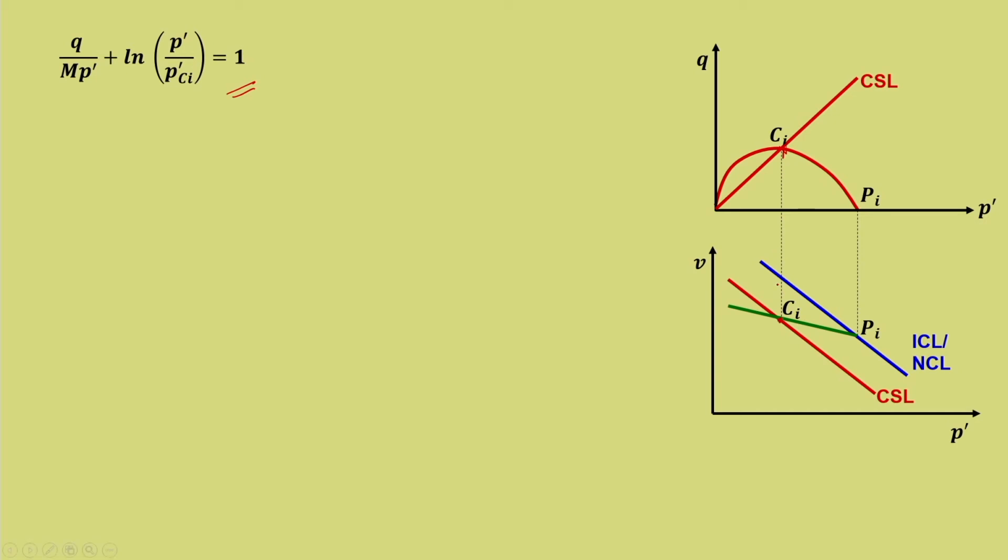So, what is the relationship? That is what we are trying to understand. When we understand the Cam-Clay model, we need to keep these aspects in mind, then only it will work. Ci is the point where the yield curve intersects the critical state line, and that is what is shown here. Now, you also need to see that this unloading line represents elasticity. The yield curve also defines the domain of elasticity. So, the crossing point is Ci.